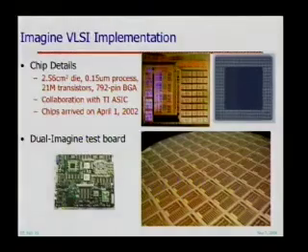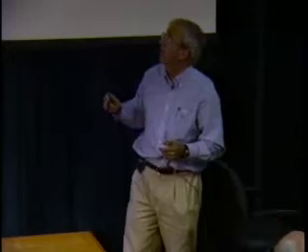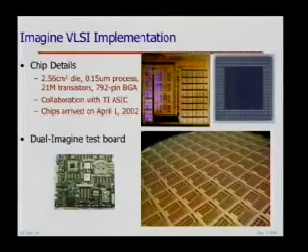And in each of those, associated with each input of each floating point unit is a small 32-bit by some number, I think they vary, I think most of them are 16 deep register file. And there's a switch then that connects those together. And so it's exactly that tree structure. The next level of the tree is a stream register file, which is a large structure just to the left of the array of clusters. And then there's a memory system with 4 synchronous DRAM channels going off to memory off the left side of the chip.